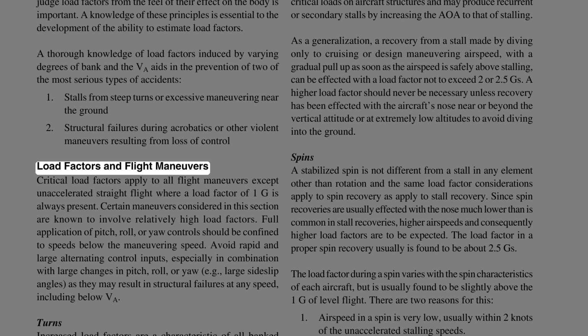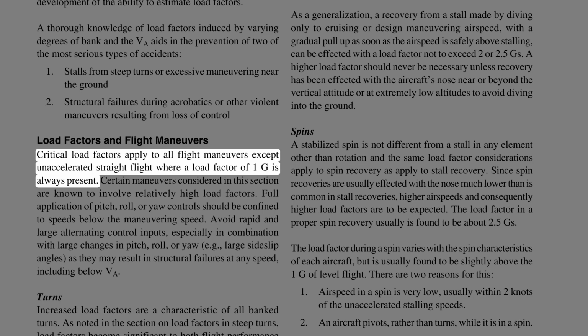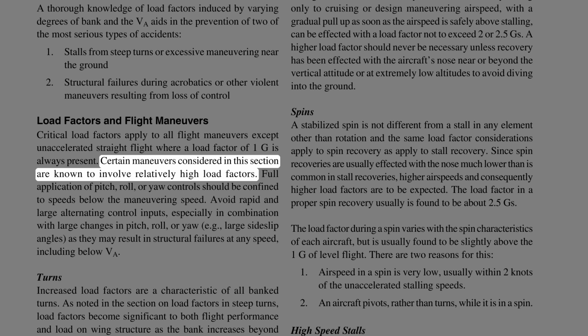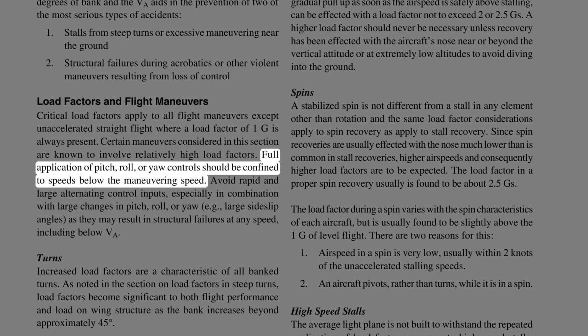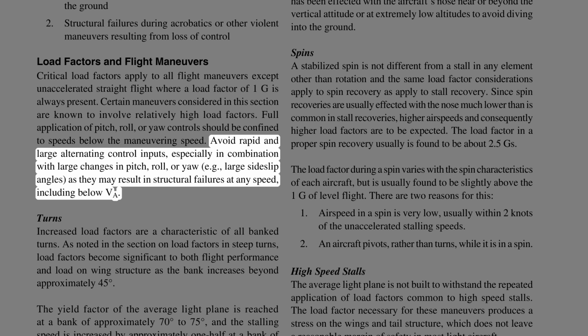Load factors and flight maneuvers. Critical load factors apply to all flight maneuvers except unaccelerated straight flight, where a load factor of 1 g is always present. Certain maneuvers considered in this section are known to involve relatively high load factors. Full application of pitch, roll, or yaw control should be confined to speeds below the maneuvering speed. Avoid rapid and large alternating control inputs, especially in combination with large changes in pitch, roll, or yaw, e.g., large sideslip angles, as they may result in structural failures at any speed, including below VA.